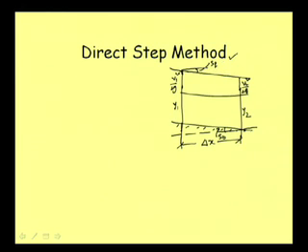Now, if I extend this line as a horizontal line, then this much is nothing but the loss, and we can write this as delta x into SF. And similarly, for this particular extent, if this is delta x and SB is the bed slope, this distance will be delta x into SB.